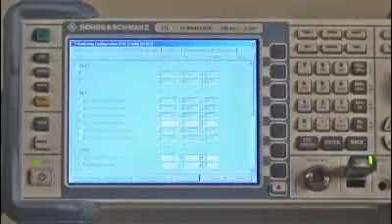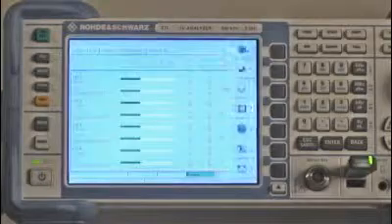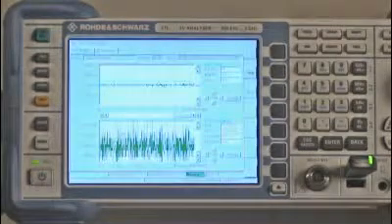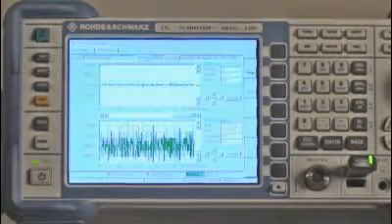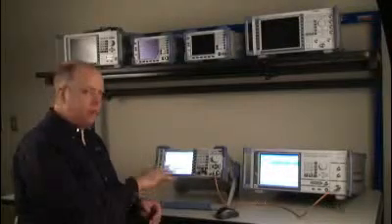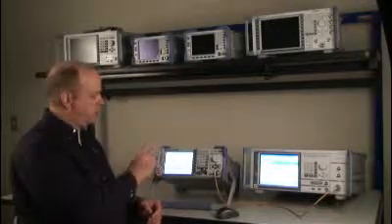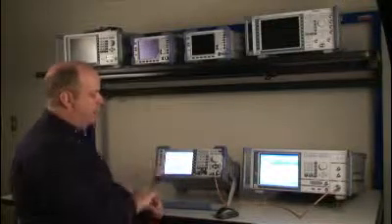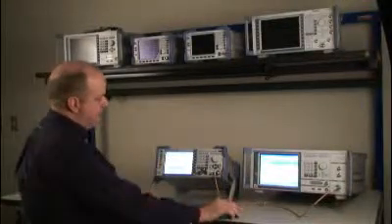Going back to where I was in the advanced area, if I wanted to tighten up my PCR jitter, for instance, I could actually go into the monitoring configuration, change those values, and my limit lines will change.